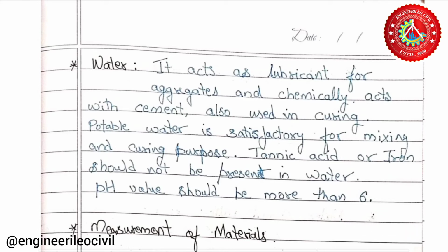Organic solids should be 200 milligrams per liter. Inorganic solids are 300, sulfates are 400, and chlorides are 200 mg per liter for concrete not containing embedded steel, and 500 for R.C.C. work. Suspended matter has a permissible limit of 2000 mg per liter according to IS 456-2000.